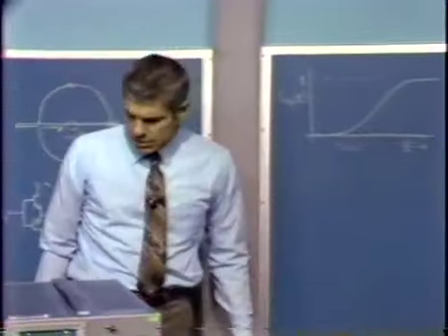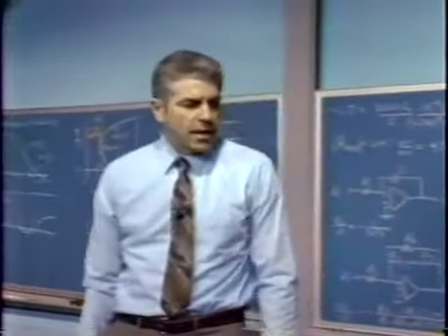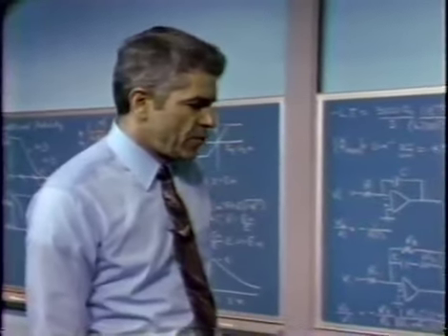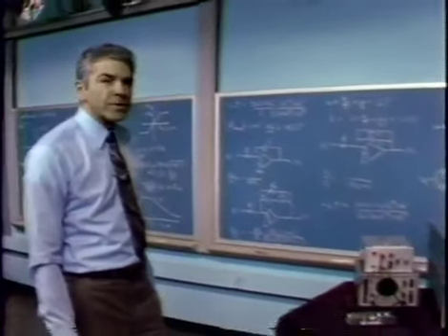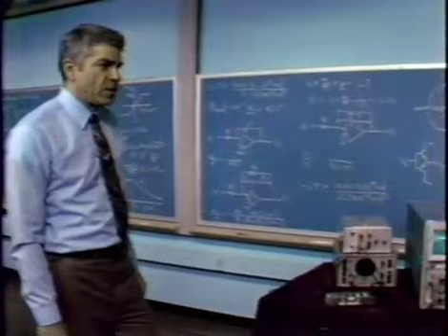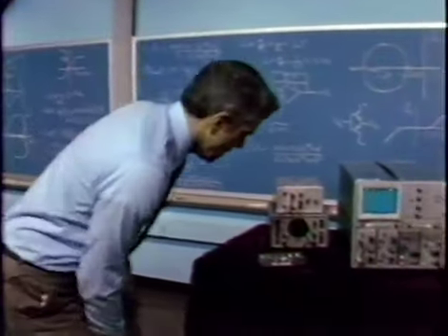Well, what this does is reverse the conditions that we indicated earlier. We now find, if we chase this through, that the high frequency crossover point becomes the stable amplitude oscillation, since the arguments that we made before are basically reversed.